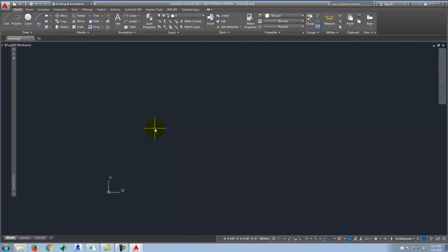In the world of AutoCAD, we're not going to draw just kind of arbitrary lines. We're going to imagine this as if it were full scale. So if I draw a floor plan, if I draw a house, the lines that I draw are actually the real size of the house. I don't do any scaling in my head. If the wall is 24 feet long, it's 24 feet in AutoCAD. So everything's full-sized, and we're actually going to pay attention to dimensions.